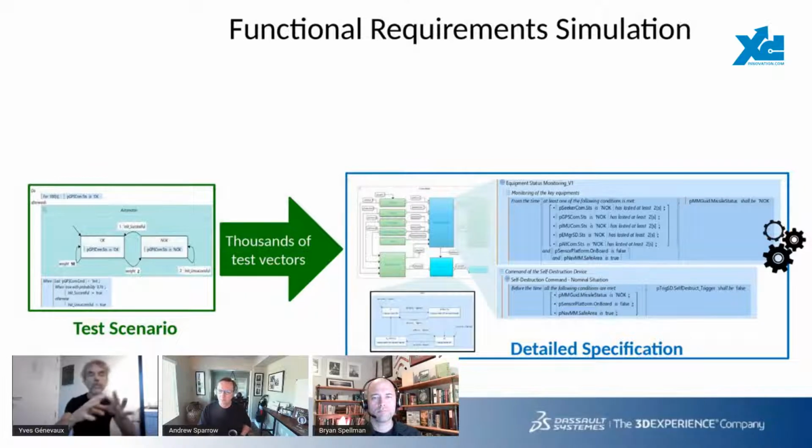What we do from Stimulus is to have these test scenarios seen as a set of constraints, defining a space within which all kinds of combinations of inputs can be generated by Stimulus and sent to the system. So it's another meaning for the simulation term, because it's an intensive simulation that can be done overnight. You're going to stress your model in a very, very powerful manner and come in the morning, and you're going to be only working on the simulations that raised some issues.